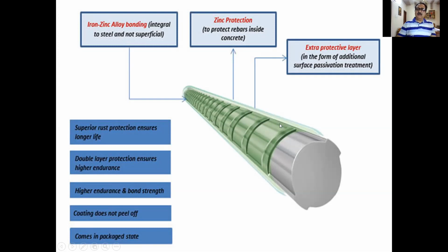So when this steel bar is inside the concrete, the moisture content and the chemical reactions are all acting upon the steel bar. They are coming in contact with the steel bar. So that's why this coating helps in mitigating the corrosion property. Corrosion can be prevented on the steel bar.